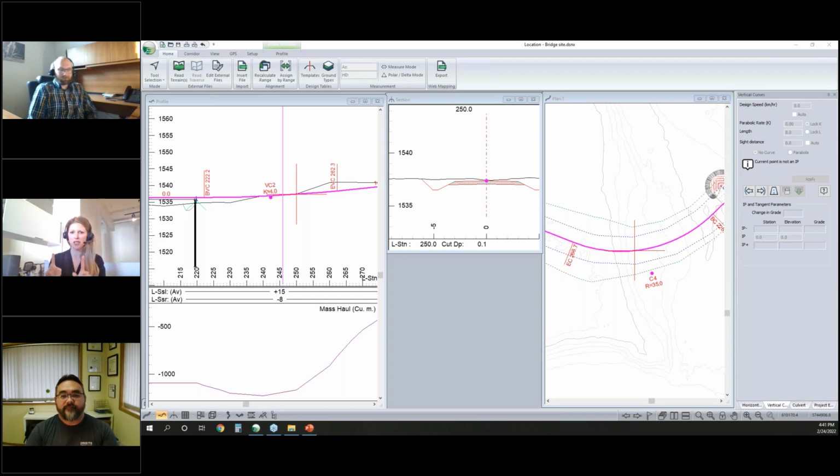Awesome. I hate to do this. We're going to do one more question because this individual typed you a paragraph, Jeremy. So apologies if I read this terribly. It says, Jeremy, my understanding is that when embankment is constructed on peatlands, they can include 1, constructing the embankment directly on top of the existing peat, 2, excavation of peat and replacement with a more suitable base and sub-base materials, and 3, geosynthetic reinforcement of the embankment on the peat. So the question from this is, which strategy do you recommend based on the height of the peat, traffic, season, or hauling distance?